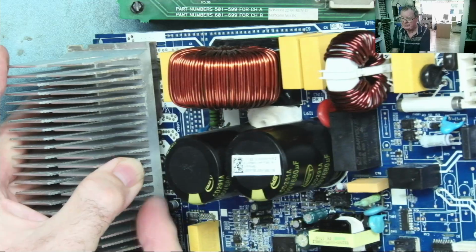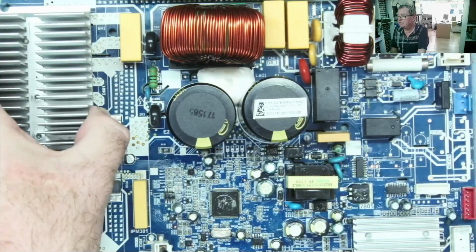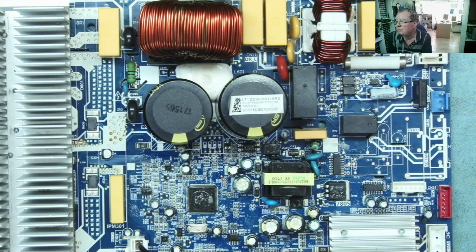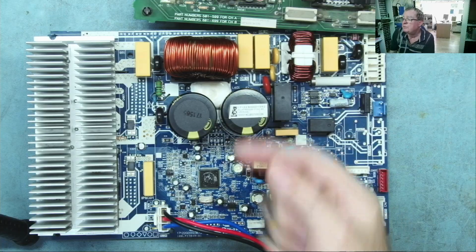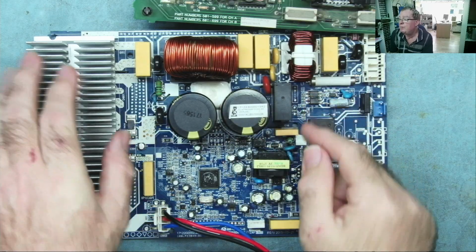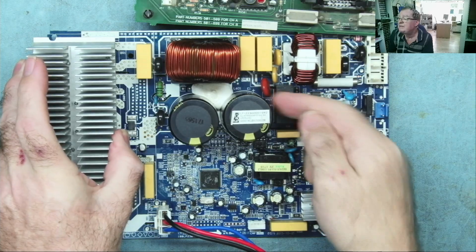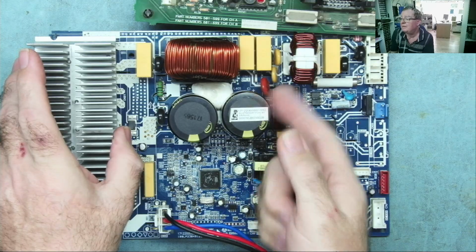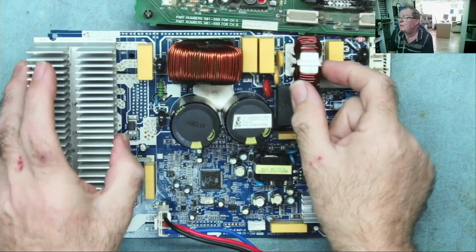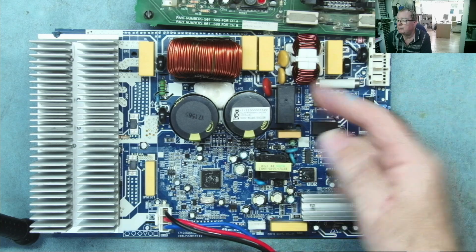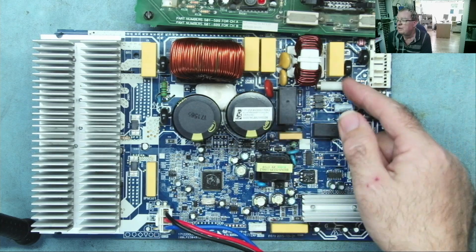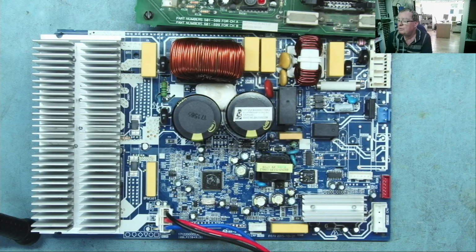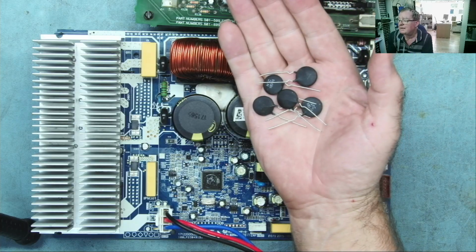Quite often in the big switching devices under here, and that short circuit will cause a massive inrush of current when you switch on. Yes, there's a fuse, but the current is flowing through the fuse and through these things, and there will be one on here. This one's there, look, PTC. That's a PTC rather than NTC. There's one there, and all the current flows in that way. So depending on which gives up first, the fuse or the thermistor, one or the other or both will blow. Okay, so that's the other place you'll find these.